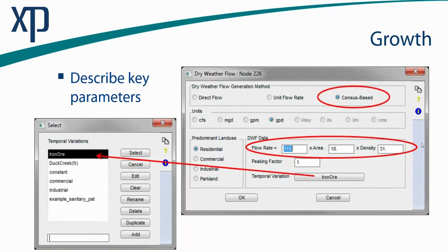Peaking factors then become very important if we want to assess wet weather, and I'll talk a bit more about those in a moment, but traditionally dry weather flow is a simple singular peaking factor, but some engineers will ramp up their peaking factors for wet weather flows by simply adding a multiplying factor of 5. And how right or wrong that is for your location, well, you'd need to hopefully have a good understanding of your catchment and the constraints that your infrastructure is based on.